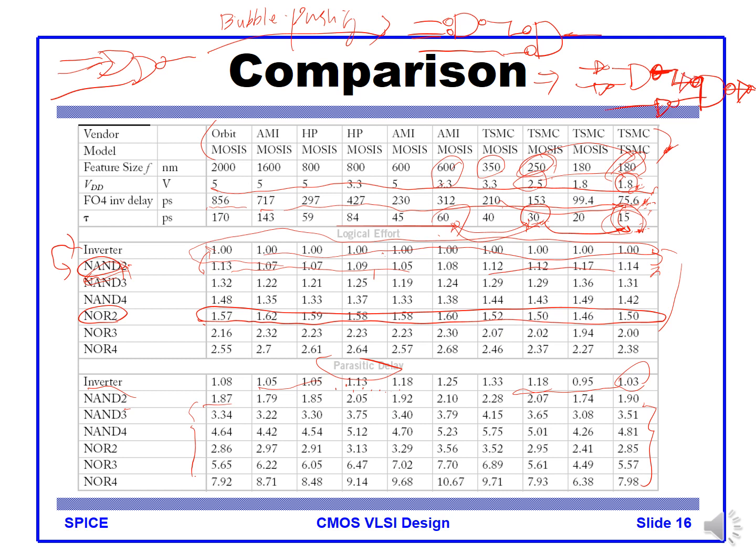You can always transform the logic with the NAND gate and inverter, right? So it is useful to construct any logic you want, right? Even the inverter can be constructed with the NAND gate. If you are lazy and you don't want to design anything, then you just put an inverter at the input and tie the inputs together. That will be equivalent to an inverter, right? Stuff like that.